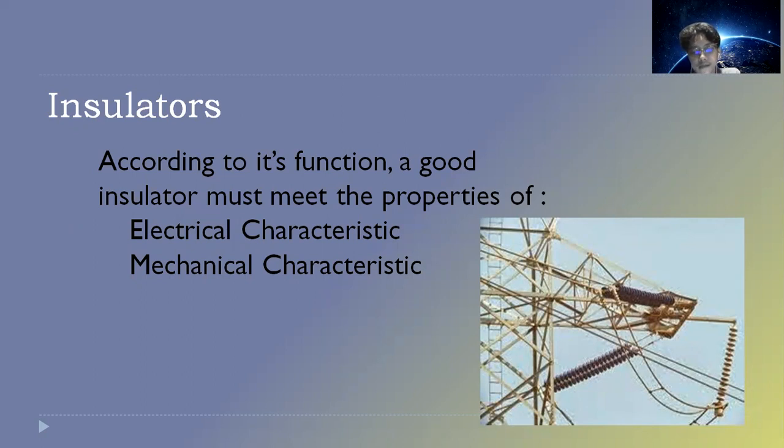So in this capacitor, the capacitance is magnified by pollutants as well as air humidity on its surface. If the insulation value decreases as a result of pollutants or damage to the insulator, there will be an insulator failure which may eventually lead to interference.